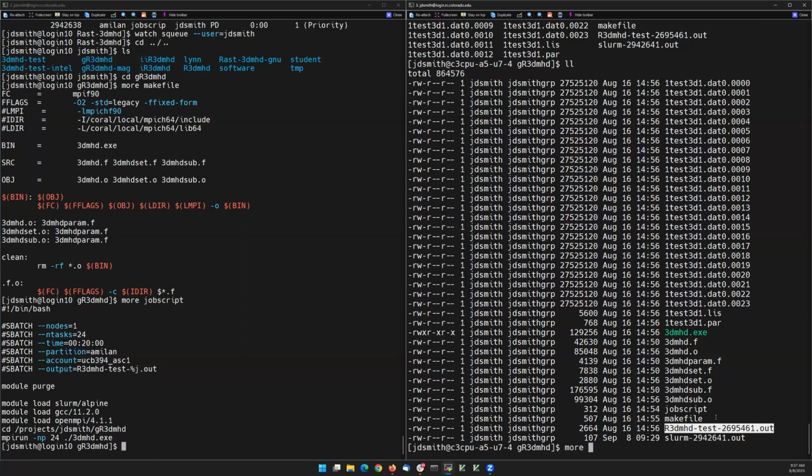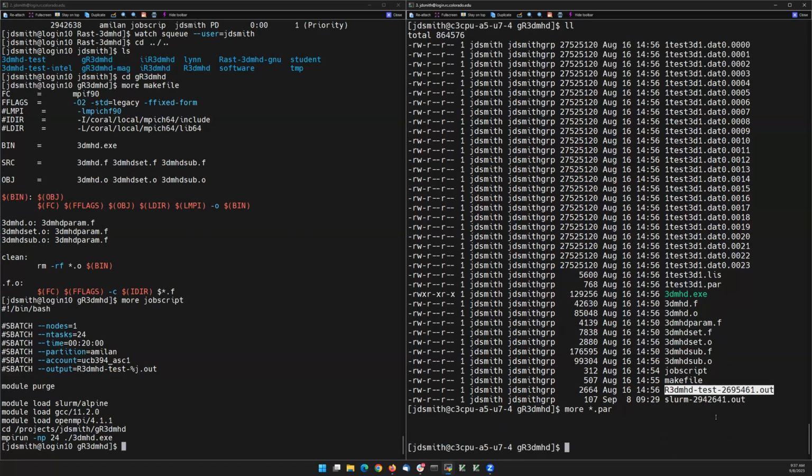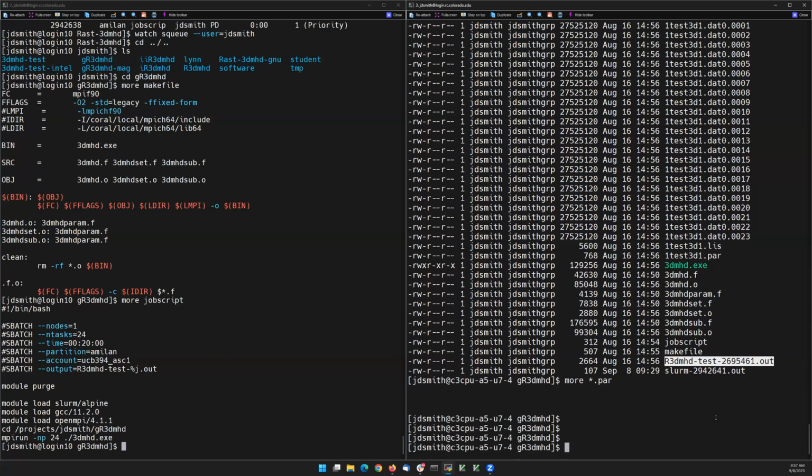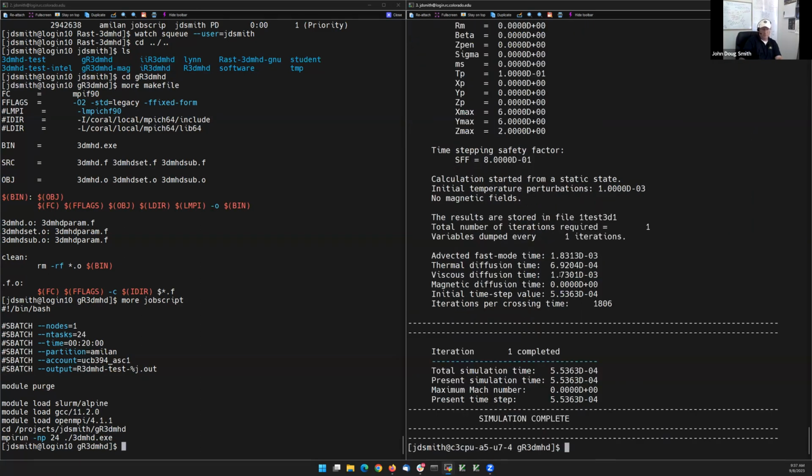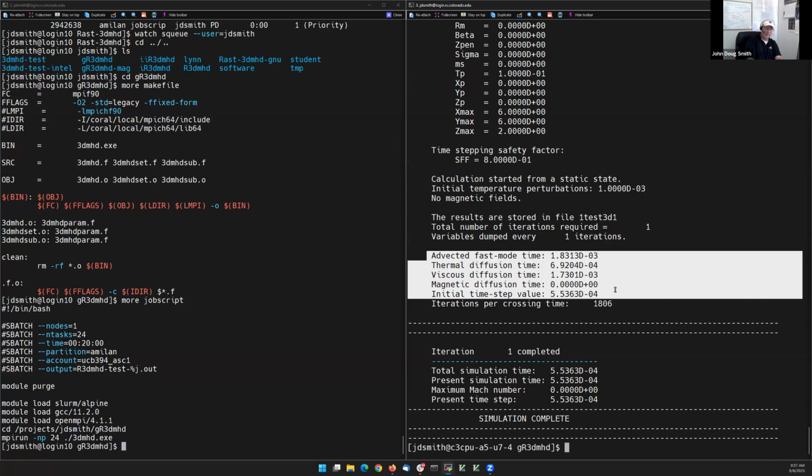I have a question. If teams make modifications to run the code on their GPUs, what do they need to watch for to make sure that everything is correct? So on the GPUs, these numbers right here are excellent numbers to use for verification between simulations. These should always be the same for the exact same simulation. So if you make a change to the code and you want to verify that your changes are reproducible and accurate, you can compare them to the unmodified code here.